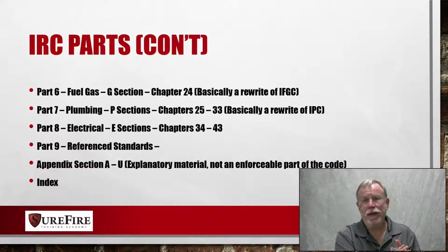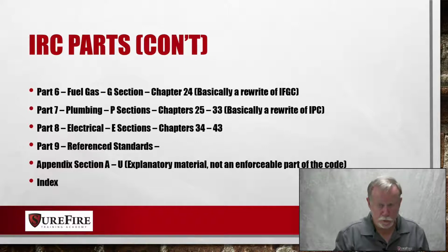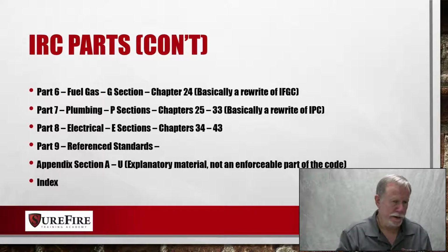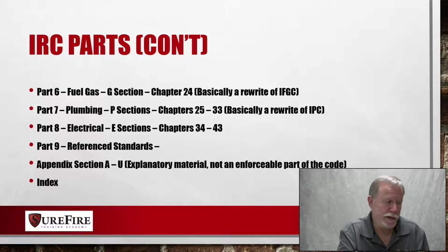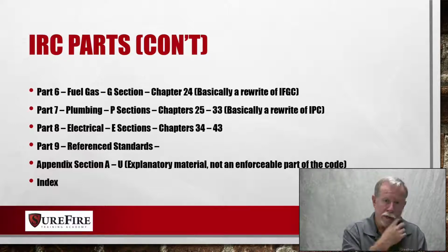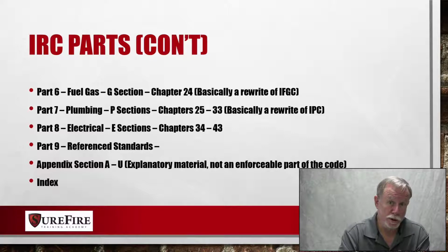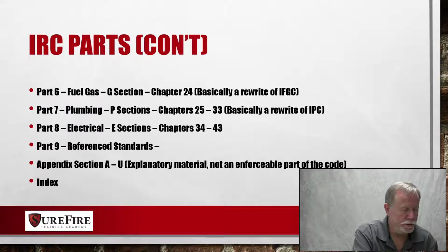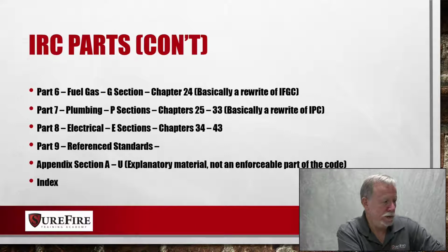For example, with gas pipe sizing tables, I think the longest length in that section is maybe 200 feet, where if you look in the International Fuel Gas Code, which is applicable for commercial stuff, you'll find gas piping lengths up to at least 1,000 feet, maybe even 2,000 feet. But much longer pipe lengths, things you wouldn't find in a typical residential home.